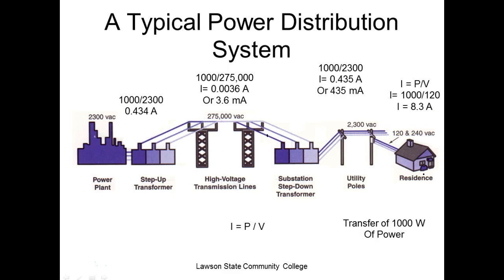So that's why we change voltage. If I had a device designed around 240, or a device designed around 120, the 240 device would require less current for that power. You understand that? So all your high wattage devices are designed to run on what? 240. Is that going to save you money?